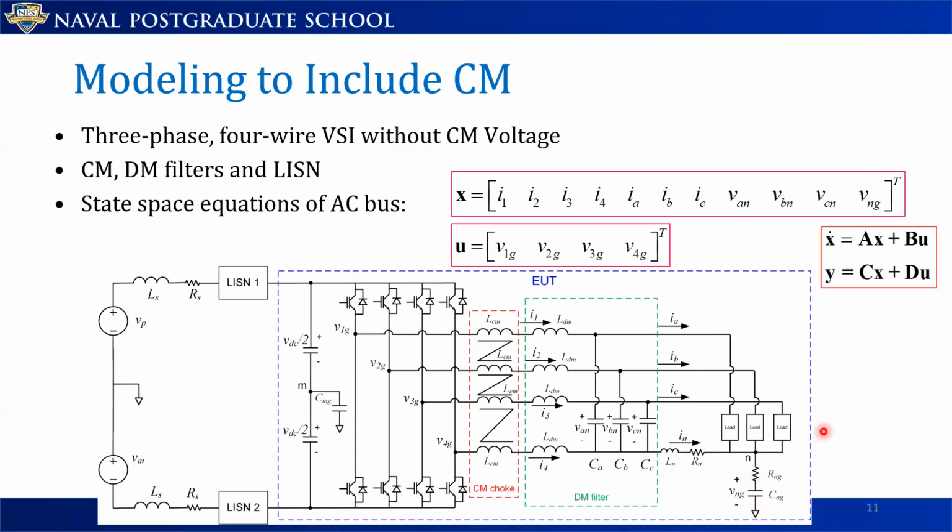But there are other papers that have been written even recently on this topic, on how to make experimental measurements to come up with the frequency response. So you take a load, you apply some different frequency voltages, and then you look at the frequency response, you plot, and then you try to match with some Bode plots with the lumped parameters. That's one way. But I know there are other more sophisticated ways in the literature that people have done this. So I invite whoever asked the question to do a thorough literature search. There is a lot that was done on this topic. Okay, thank you.